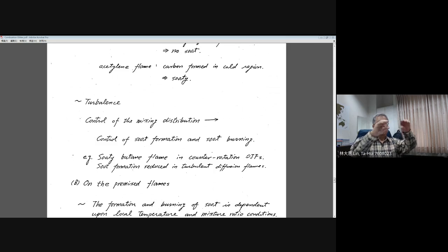I hope you remember, originally the flame is blue, but when you increase the flow rotation, the swirling behavior will force a reverse flow inward near the stagnation plane, which increases the residence time in this region near the stagnation plane, actually the fuel side of your diffusion flame.